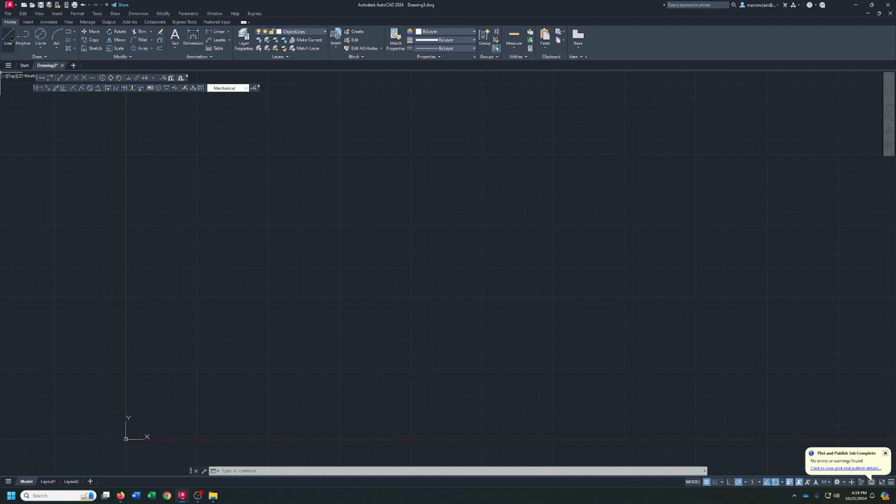Let's get on object lines first, and we're going to draw a line here, and it's going to be 3 inches. We're going to go up 1 inch. We're going to go this way, 45 degrees. So let me set Pac-Man over here to 45. There we go. It doesn't really matter how far, because we're going to offset the bottom. Offset it 2.5, and then we're going to trim this and this. All right, now I'll offset the bottom 0.5.